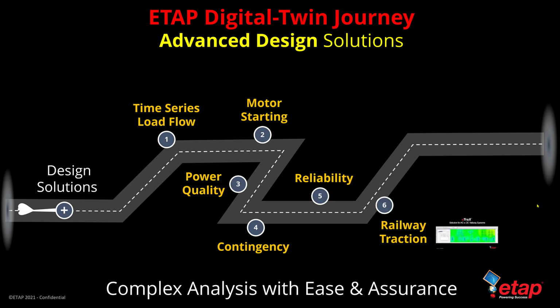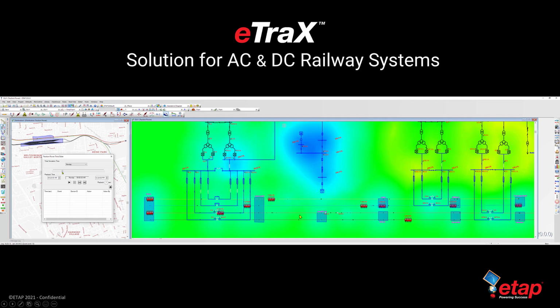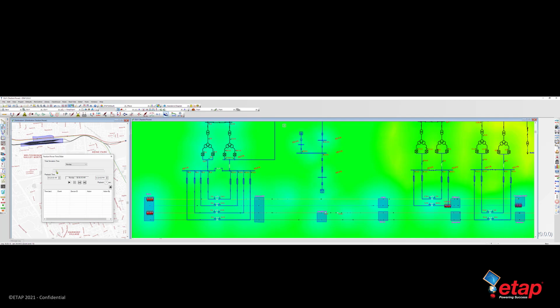utility systems, railway traction or E-Track study, where you can simply take the electrical system model, combine it with GIS as well as the single line diagram, and then perform a multi-domain simulation where we are doing mechanical and electrical simulation of the train movement as well as its impact on the electrical system at the same time. And by combining the DC system, you can then also bring in the uniqueness of having an energy storage device or wayside storage as part of the electrical model design as well as the analysis.